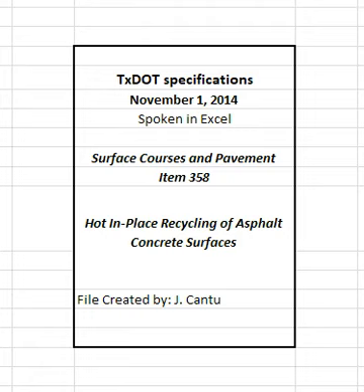4.2.1 Sampling. Before bidding, the engineer will provide material and pavement information obtained from roadway cores, such as layer thicknesses, gradation, asphalt content, and recovered asphalt penetration of the pavement to be recycled, using the Construction Division's protocol and guidelines. Additional cores may be taken by potential bidders to obtain further information on the material to be recycled when approved.